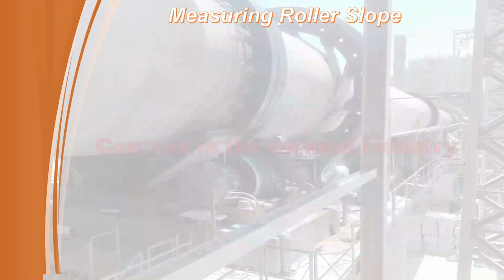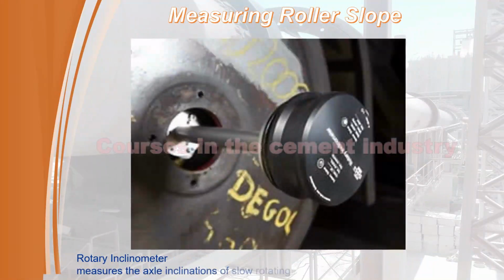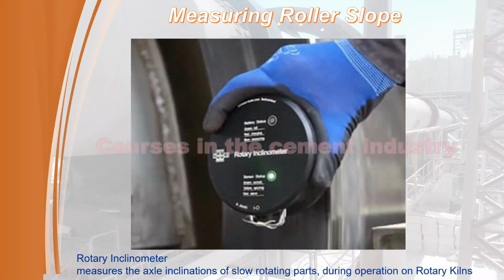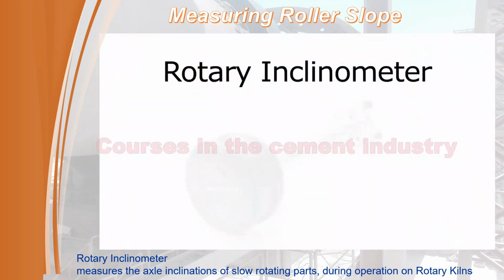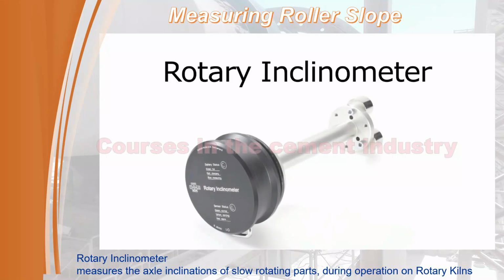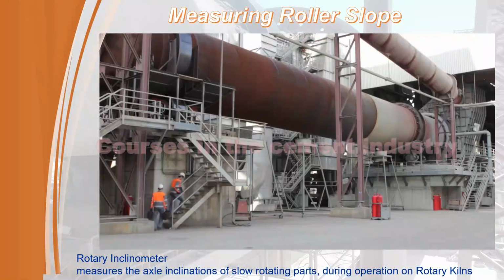Another device. See in the figure. Rotary inclinometer. It measures the axial inclinations of slow rotating parts during operation on rotary kilns. See this video on how measuring by rotary inclinometer works. The rotary inclinometer is a measurement tool which measures the axial inclination of slow rotating parts such as rotary kilns during operation. It measures deviations in vertical direction with a high accuracy, which makes the alignment work much easier.